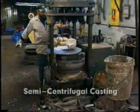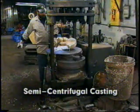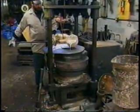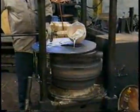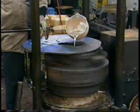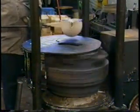In semi-centrifugal casting, the mold surrounds the casting and controls the shape being cast. The mold typically rotates horizontally, and the metal is usually poured through a central gate. Coring is required if the shape is hollow.